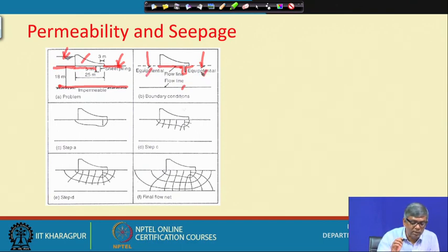So, these are the things. Now, this is an equipotential line, and this is also an equipotential line. If I want to draw a flow line, it should come out at right angles from here. So, the starting point should be at right angles, and the line will go like this, and when there is an obstruction it will not go straight and come down like that; it will smoothly pass over this and reach here. That is the first trial of one flow line.